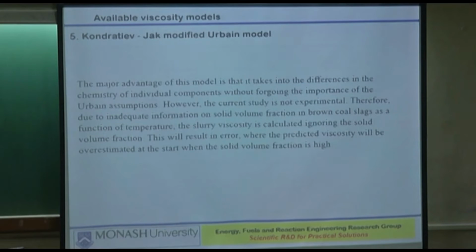It slowly becomes liquid. And then, if you keep the temperature high long enough at that point, gradually the solids fraction will reduce, and everything will become more and more liquid. So that has to be understood, that the proportion of the solid fraction is a function of time.